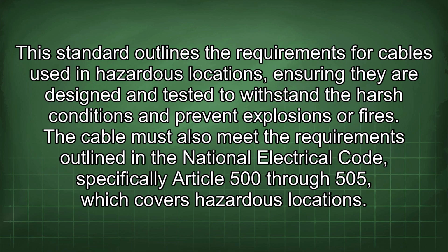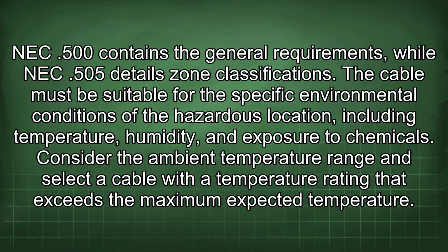The cable must also meet the requirements outlined in the National Electrical Code, specifically Article 500 through 505, which covers hazardous locations. NEC 500 contains the general requirements, while NEC 505 details zone classifications.